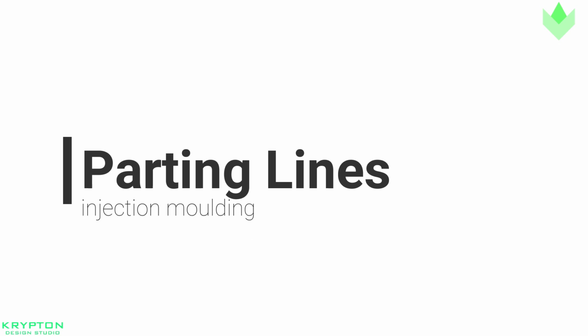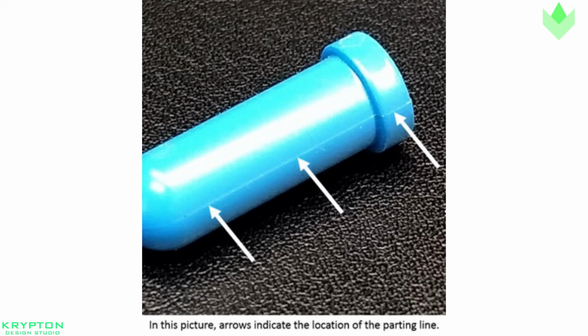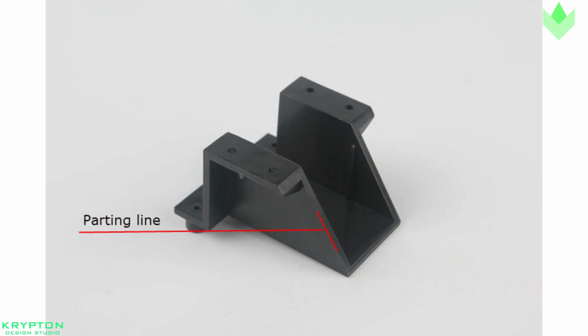Parting lines. A parting line is the line of separation on the part where two halves of the mold meet. The line actually indicates the parting plane that passes through the part. While on simple parts this plane can be a simple flat surface, it is often a complex form that traces the perimeter of the part around the various features that make up the part's outer silhouette. Parting lines can also occur where any two pieces of the mold meet. This can include the side action pins, tool inserts, and shutoffs.